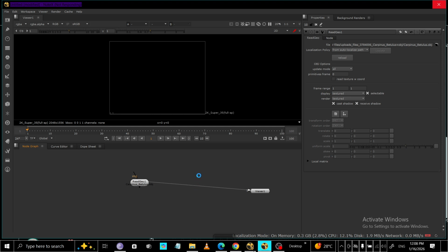If you don't see anything at first, make sure your viewer is looking at scanline render, and remember that the render depends on the scene's camera and visibility. With default settings, Nuke uses its default camera and lighting, so you'll still get a basic 2D pass.